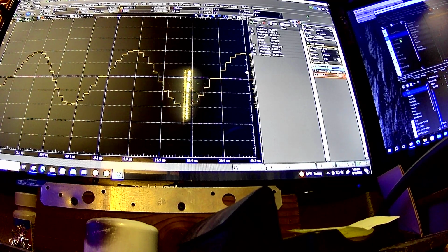I could do a whole video on that topic alone, what your resolution limits are at every given frequency, what's stable and what's not, for a given number of samples. So it gets complicated if you're trying to make subtle adjustments in frequency when you have a fixed sample rate. So it helps if you can fine tune the actual sample clock rate of your DAC externally.